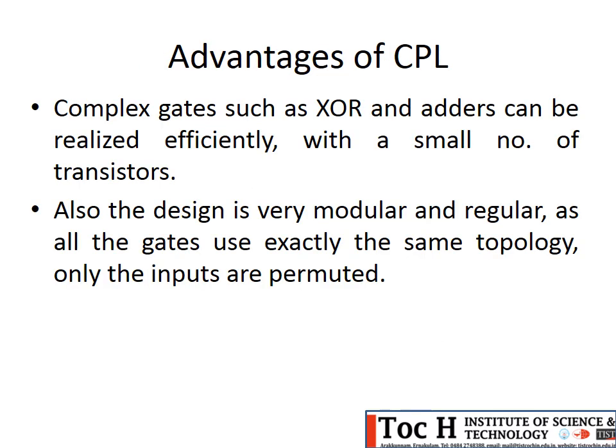Now regarding the features of complementary pass transistor logic, you have noted one basic advantage: the configuration used to design any logic function, AND, NAND, OR, NOR, XOR, XNOR, is the same, using only N switches. The only difference is in the position of the inputs and the control signals.